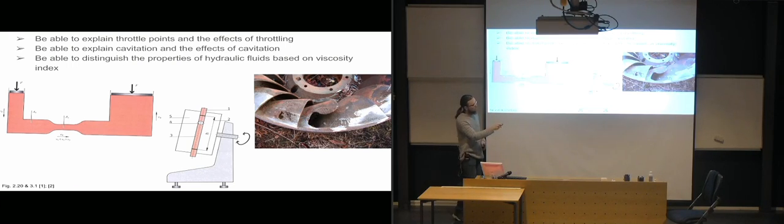And then when you turn it around this axis, so you just flip it 180 degrees so that the ball ends up at the top, then the ball is going to slowly slide down the tube, and it's basically the speed of the ball that tells you what the viscosity is going to be. So then you'll have some tables where you can calculate what the viscosity is going to be. So this, of course, has quite a lot to do with the system that we're using, what kind of fluid we are going to use.